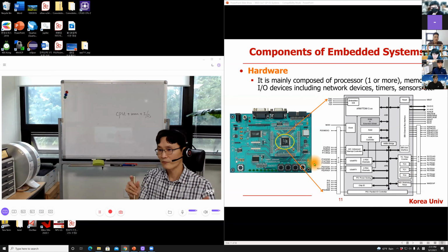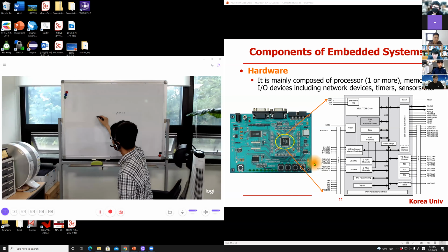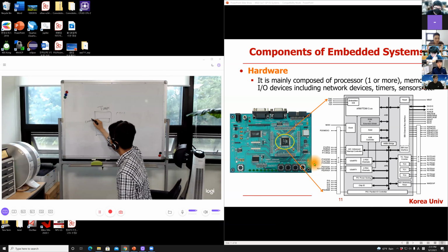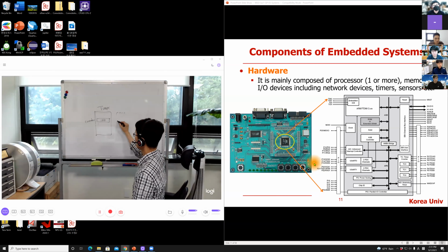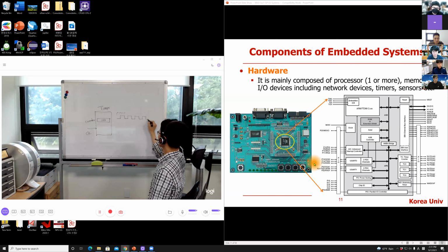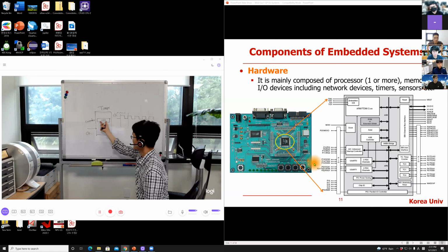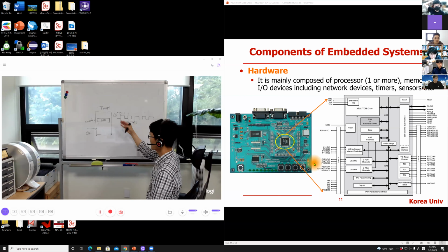Okay, so how does the watchdog timer work? In a timer I/O device, you have some counter register, right? So you set, for example, 100. Then the clock is coming in, CLK. Then this timer is counting down from the number you just programmed, right? So 100, the next number is 99. Hardware is decrementing. Okay, there is a subtractor, adder, right?